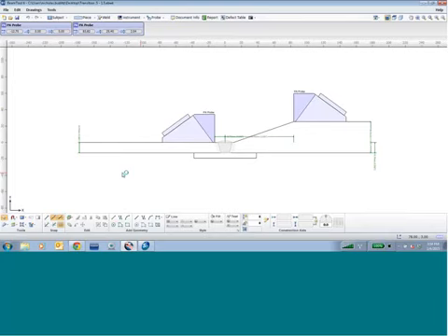You have a 1/2-inch part welded to a 1.5-inch part with a very vertical bevel on the weld, plus you have a backing bar. So this is every UT data analyst's nightmare. You have different material thicknesses, a vertical joint prep, and a backing bar that you have to deal with.